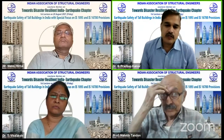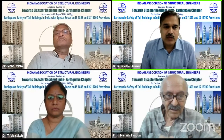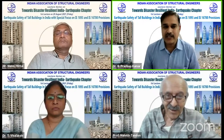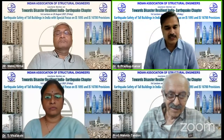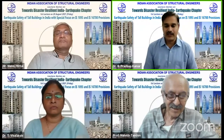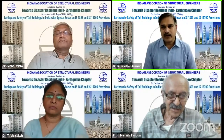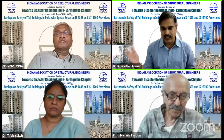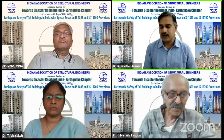So buildings with large podium will have a lot of missing mass. So that is the reason why it is there. But still, maybe an amendment will come. Amendment means we need to study that properly and then give the real behavior. So if possible, I request the consultants to have a separate discussion so that we see whatever building they are designing, what value they are getting. So missing mass correction is an important thing there. Yes. So especially podium, whether it has retaining walls on the side, or it is completely rigid at its base. These are the factors which we need to take into consideration.